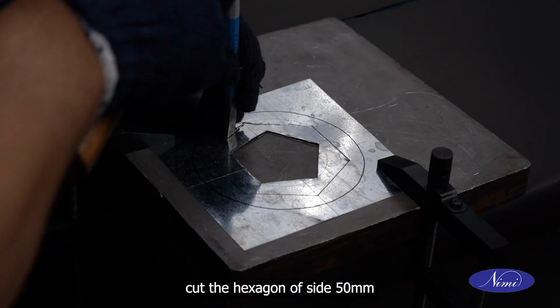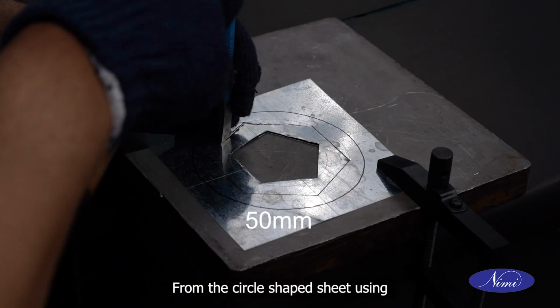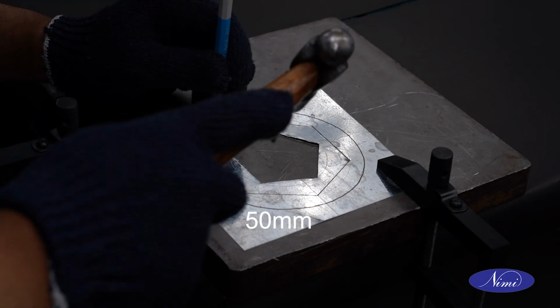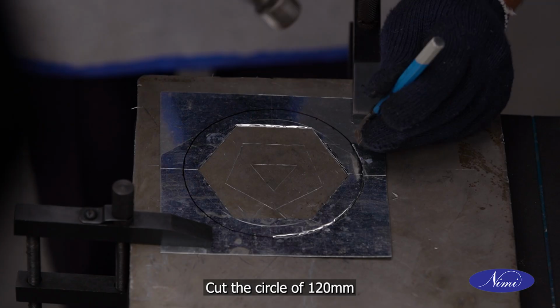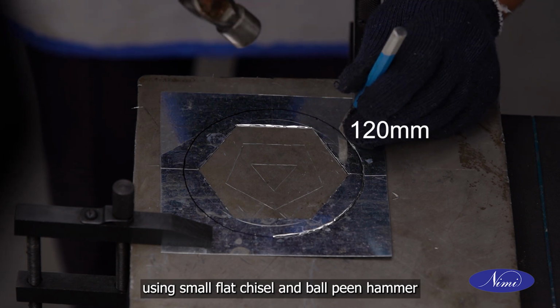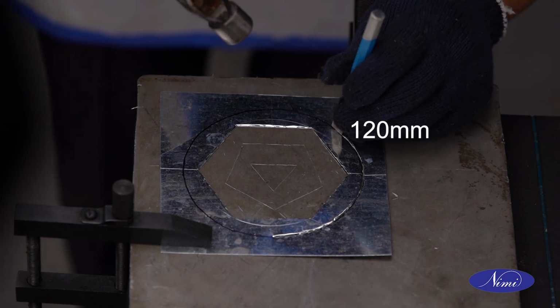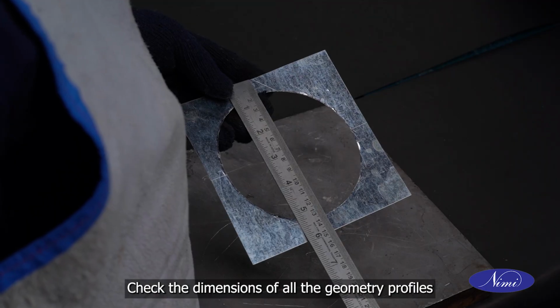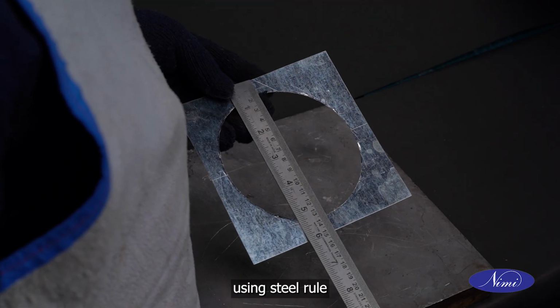Cut the hexagon of side 50 mm from the circle-shaped sheet using flat chisel and ball-peen hammer. Cut the circle of 120 mm using small flat chisel and ball-peen hammer. Check the dimensions of all the geometric profiles using steel rule.